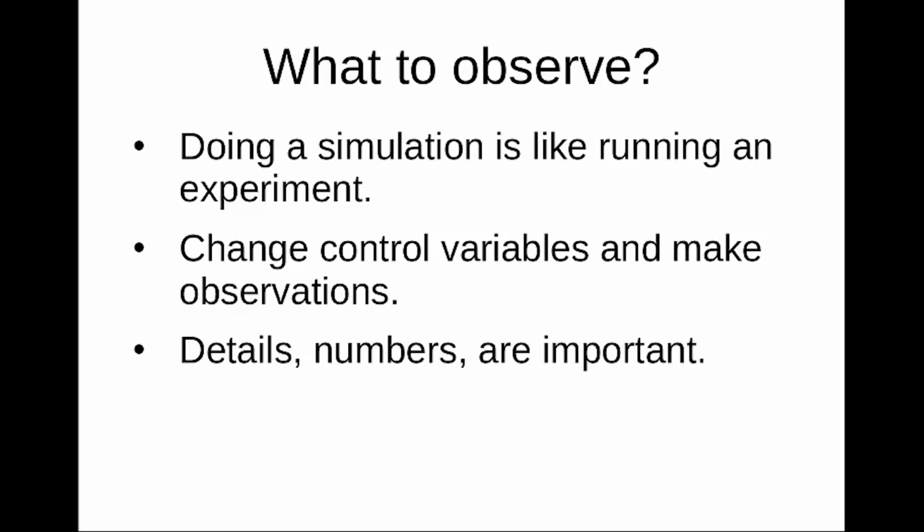So if the numbers are not making sense, for example, if the currents or voltages observed are huge values or very minuscule values, we can conclude that there is some problem somewhere in the simulation setting or in the model itself. So you will have to look at that issue further and then correct it.